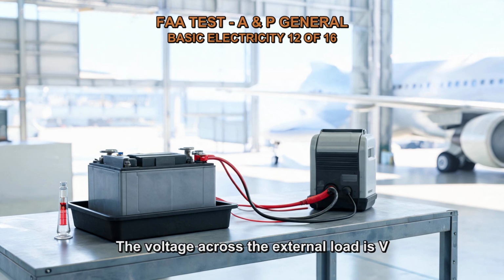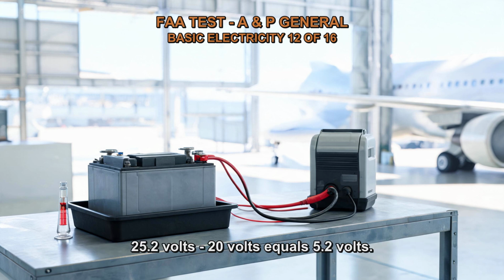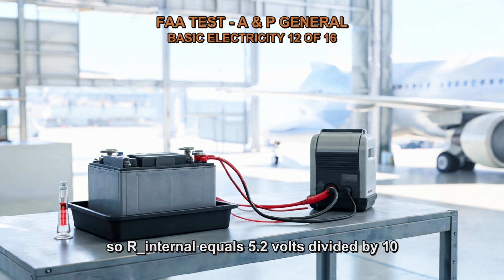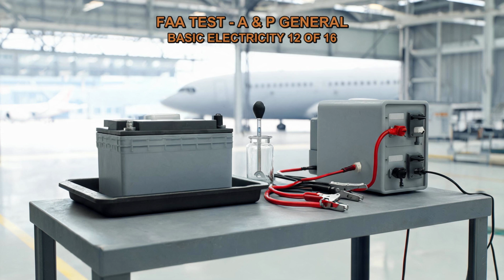The voltage across the external load is V equals I multiplied by R, equals 10 amperes multiplied by 2 ohms, equals 20 volts. The total no-load voltage of the battery is 12 cells multiplied by 2.1 volts per cell, equals 25.2 volts. The voltage dropped across the internal resistance is 25.2 volts minus 20 volts, equals 5.2 volts. Internal resistance equals voltage drop divided by current. So R_internal equals 5.2 volts divided by 10 amperes, equals 0.52 ohm.